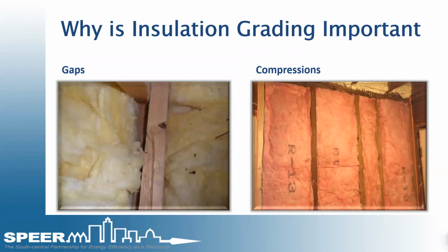Not really. I mean, there is a little bit of heat transfer that's slowed down, but when you've got holes in the walls, you've got bad insulation, you've got holes in the air barrier, that heat is going to transfer through really quick. The important part of that, and what a lot of people don't understand, is the more compressions and the more gaps that you have, you start to move the condensation point within the wall.